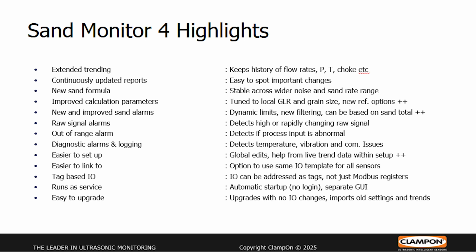For example, if there's a lot of vibration that causes false readings, the sensor can measure that up front and trend it so that we can pick that up with the new software. If there's an abnormal temperature on the sensor, for example, we're not logging that in the software. So you get a lot of extra diagnostics as well.